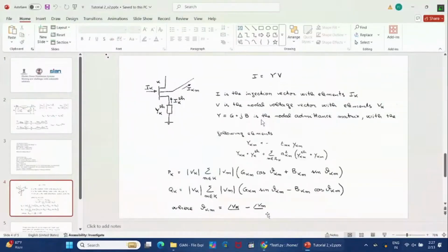We write this equation because we want it to give P load in the receiving bus, and we write this equation in order to have 0 reactive power in the receiving bus. So our equations are the difference between this equation and the set value, and fsolve finds the 0 of this difference. So the vars data takes this constraint as equality.